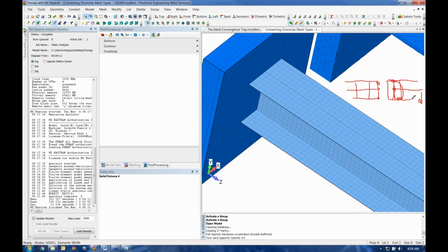I've generally used the same thickness as the rest of my plate, but as with all of these topics, it's good to explore the different thickness values, explore the different techniques, and see where the sensitivity really is. What you like to see is using a range of different thickness values, not seeing a huge range of stresses, letting you know that the model is kind of insensitive to this specific parameter.